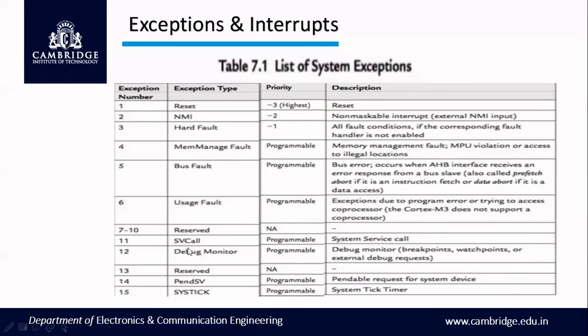And SVC is for getting into privileged access level. Debug is for monitoring the debugging operations. And PendSV is to tell the system that there are services that are pending. And system tick is the system tick timer, which is used for generating the tick time. Right. So these are the exceptions.